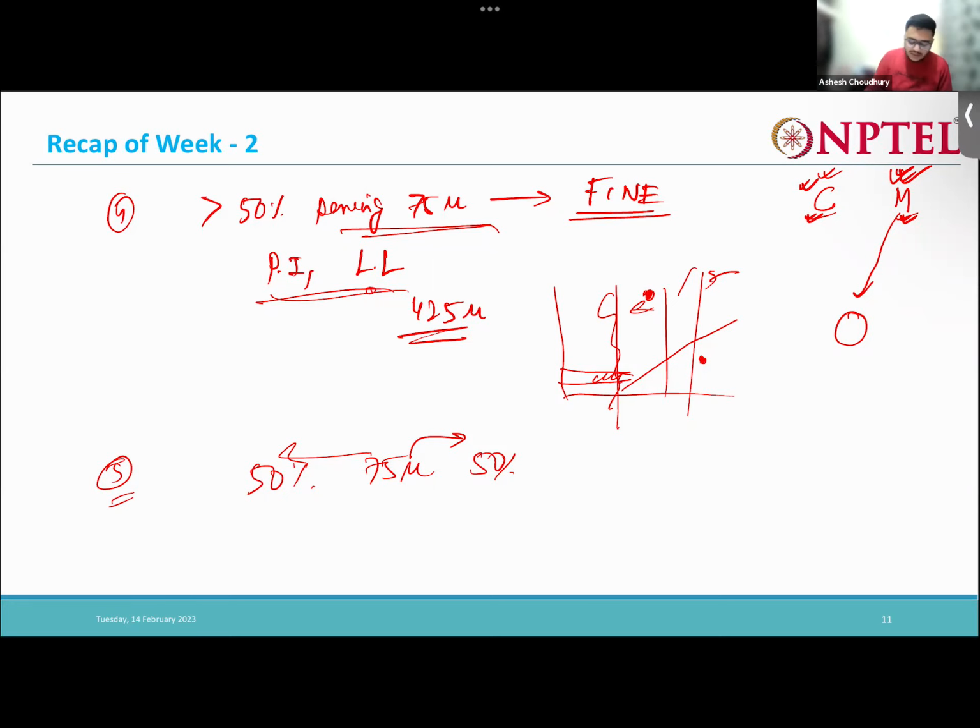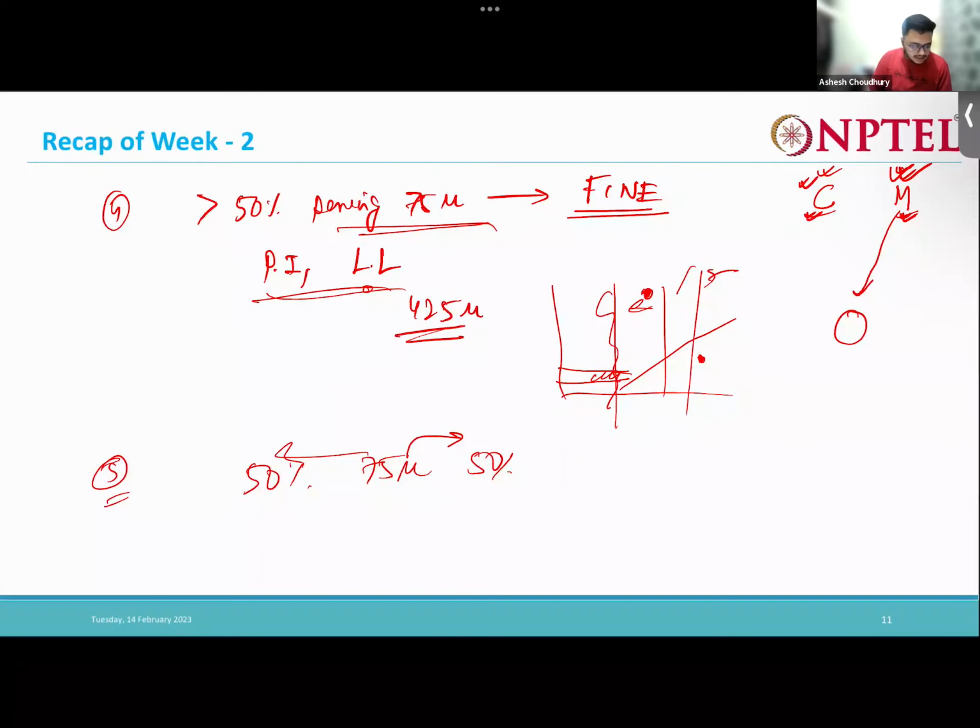Then what we need to do is find out the liquid limit and classify it as low, intermediate or high: below 35% L, between 35 and 50 I, greater than 50 H. And then you assign your dual symbols, like GM-ML, that is silty gravel and also low plastic silt. So this is a theoretically possible case, but almost impossible in practical life. So this was our last case. This ends the main classification part.